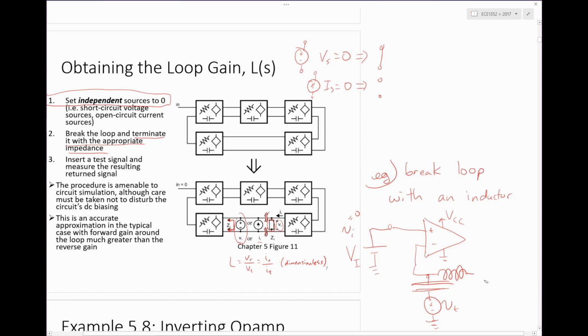Another method that I actually prefer, but it's a little bit dependent on the simulator you use. But I know in a lot of high-quality simulators, HSpice and so on, it's possible to use a resistor here that has a different value of resistance for the DC operating point analysis and for the AC analysis. They're just different parameters for the same component. And that's really nice. Then you just say explicitly, for the DC analysis, this thing has a resistance of 10 to the minus 10. For the AC analysis, this thing has a resistance of 10 to the 20. It's very clear. It's an open circuit for AC. It's a short circuit for DC analysis.